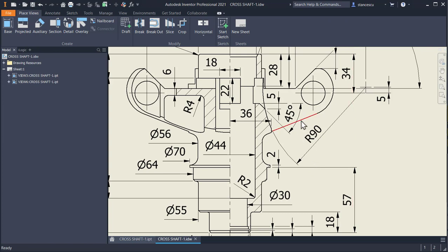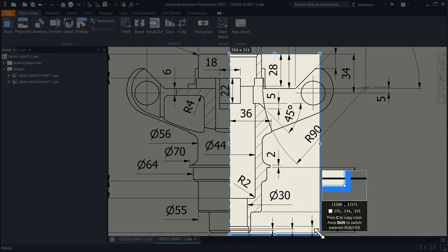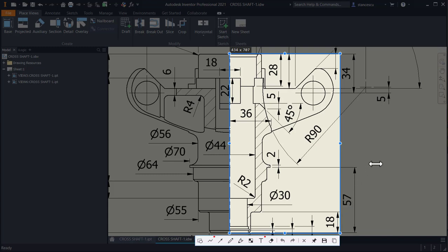and having this profile of our part, we can start by using the key F1. You look here, and this collimator appears. Use it to identify as exactly as you can the midpoint of the superior line. As you can see, I make it here. Press the left button and keep it pressed, like me. And now go down and right, so as to catch the horizontal black line. Now I release the left button.